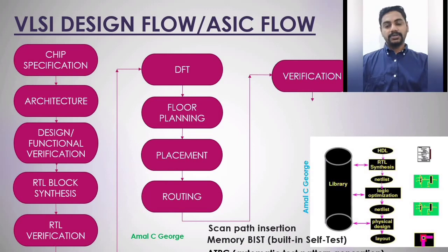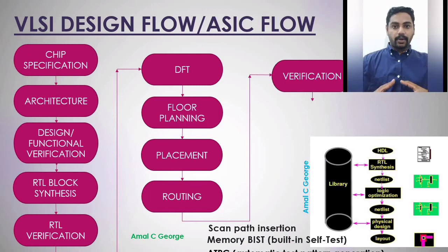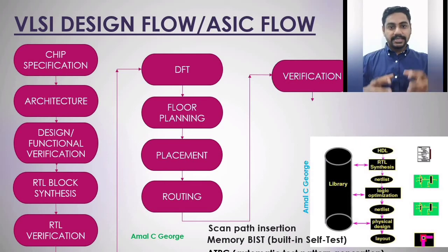The last step in our design is GDSII and post silicon validation. So in the last stage of the tape out, the engineer performs wafer processing, packaging, testing, verification, delivery to the physical IC. So GDSII is the file produced and used by the semiconductor foundries to fabricate silicon and handed to the client. In the case of post-silicon validation, this sample now goes through the post-silicon process, where another team of engineers